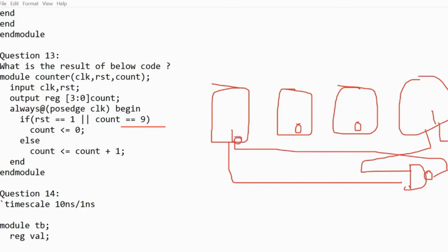Here we are using an active low clear signal. Whenever the output of the NAND gate is 0, whenever we are feeding inputs as 1 to the NAND gate, the clear signal will be activated and these two flip-flops will be reset, and all flip-flops will get 0 after reaching 1, 0, 0, 1.